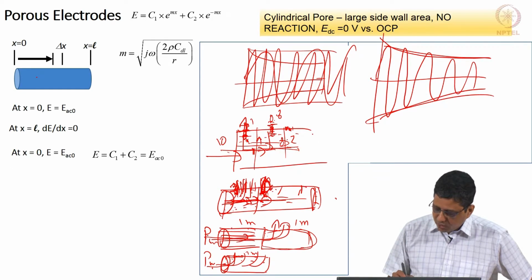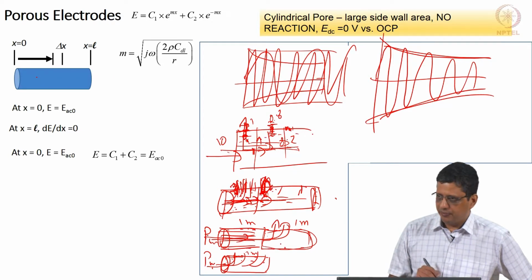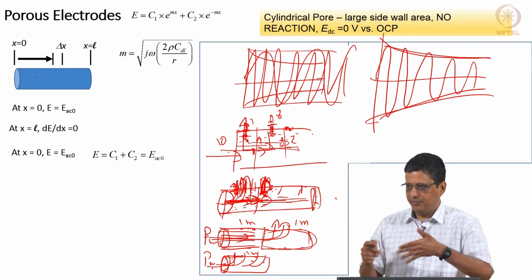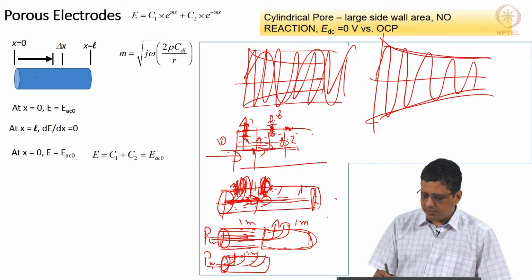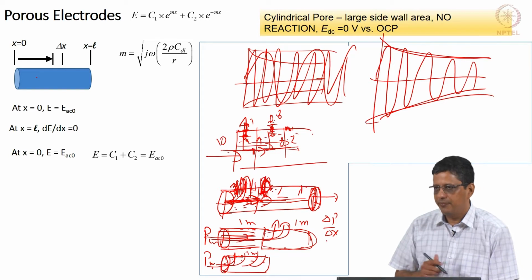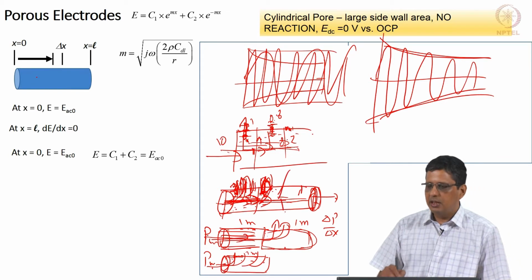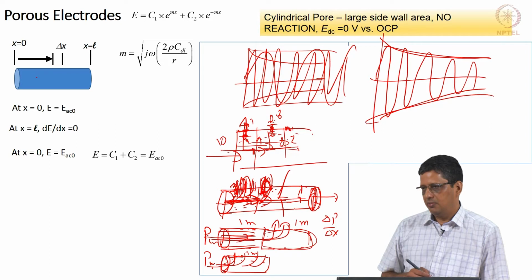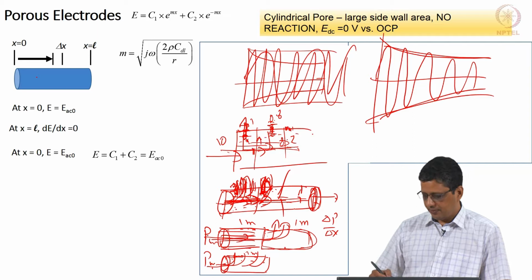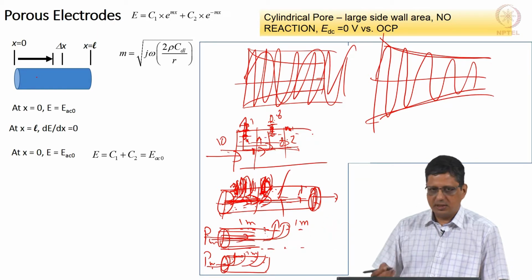Now, I can have a combined one where from the beginning itself there is pore. This will offer pressure drop, it will offer some flow here, it will offer a pressure drop here. This pressure drop will keep varying because there is flow on the side. Okay. If you look at a straight pipe, same diameter, del P by del x, when I have opening only here, del P by del x will be a constant for Newtonian fluid. When I have flow around this, del P by del x will not be a constant. That is effectively what we are accounting here. I do not know whether it answered your question, but